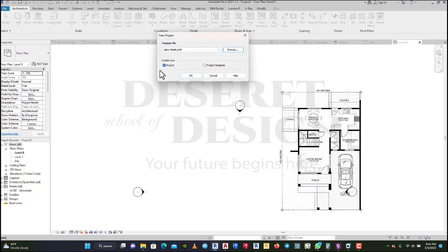Now when you open it like a project, it will still come empty, but whatever settings you've done in all those things will be in this thing, without the model. But if you open a project and there's a model inside and you save as a template, anytime you open a project, that model will be there. So you have to delete it and start all over. You need to make sure you've deleted every model out of it. Your walls, everything you've created, will still be in it. The formulas you've used will still be in it.